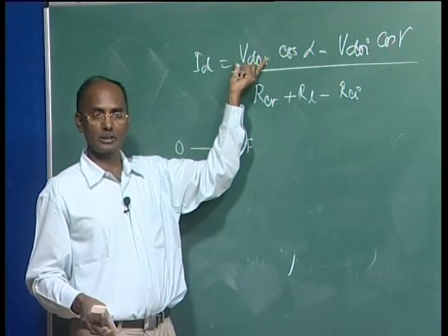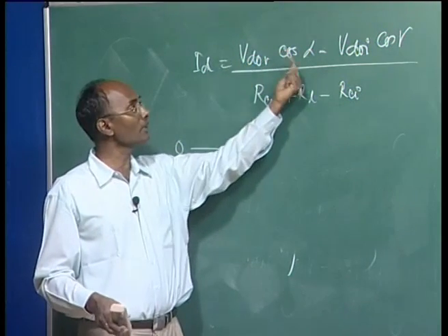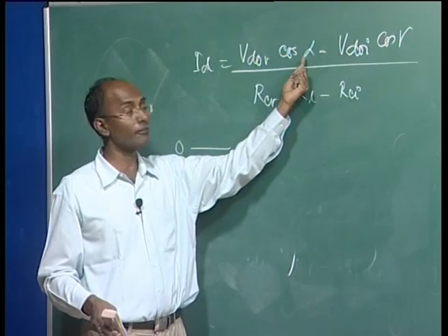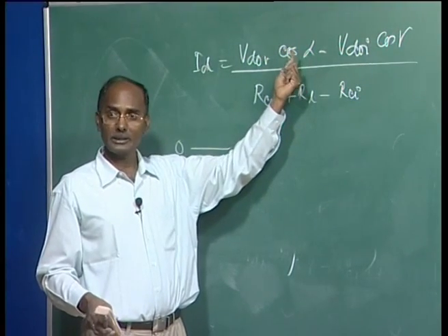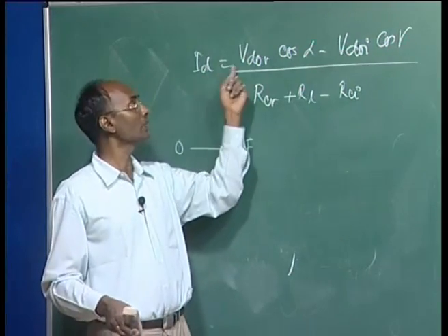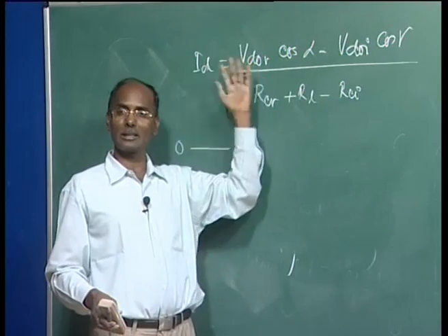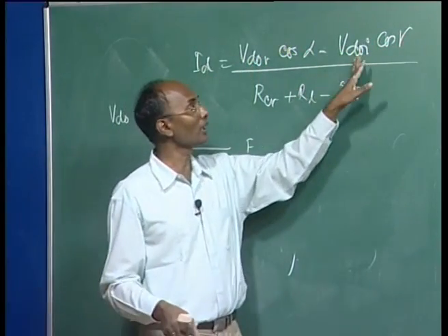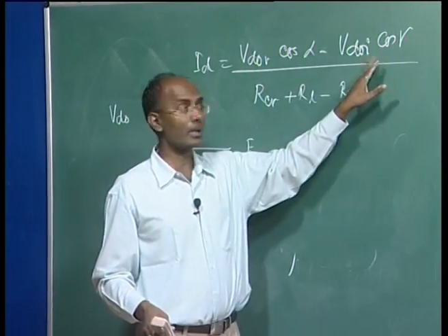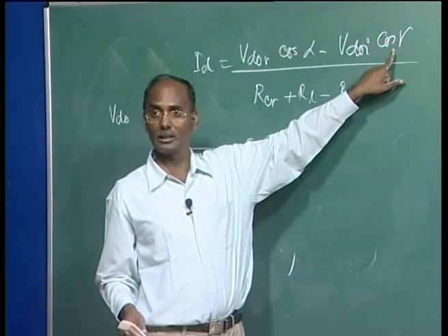How can you control this? Because we are having the tap changer. So first we have to go for this because it is very fast. If it is exhausting its limits, let's suppose it is reaching 25 degrees, then we have to try to control the voltage by this. Let's suppose this is still exhausted, then we can come to this side, because we want to maintain this constant, we don't want to change it here.